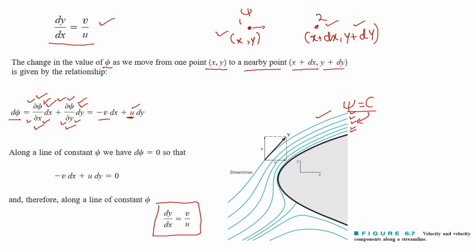So this was our stream function psi, and the stream function psi is used for two purposes. One was to represent the two velocity components in the two-dimensional differential form of the continuity equation, that was the u velocity and the v velocity, as a single term psi. And the other is to take psi along a certain line constant, and by doing that we are defining our streamlines, and by defining our streamlines, we are getting a better visualization of our flow. So this is what the stream function is used for, these two purposes.